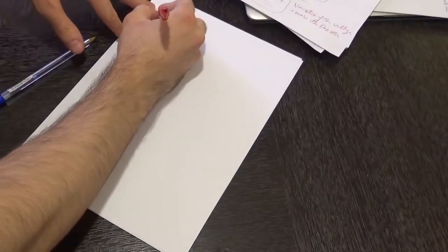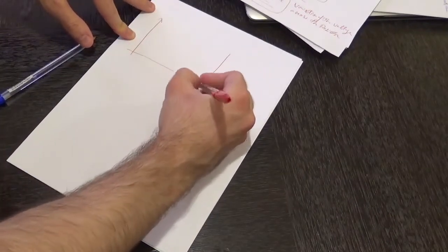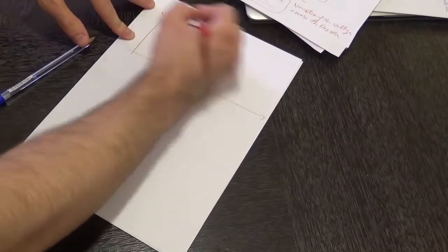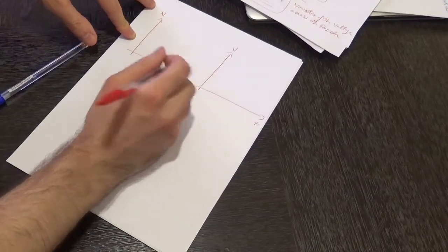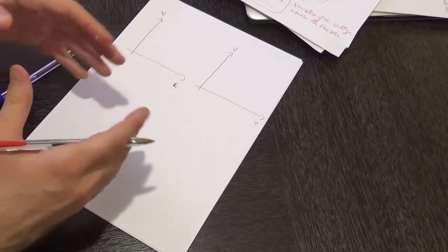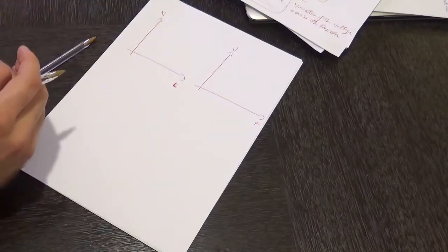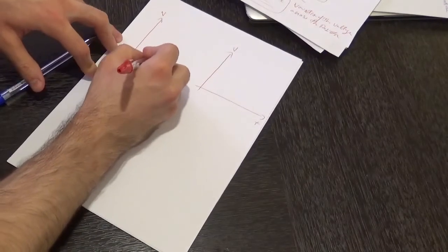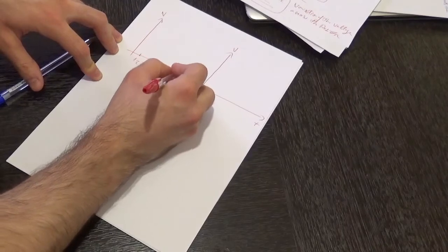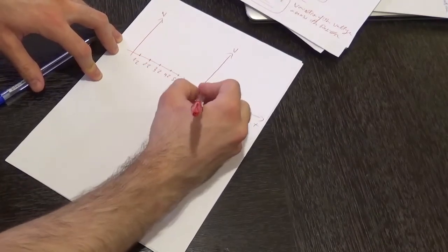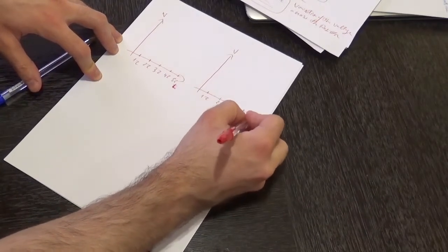Let's consider that we have the following two graphs for which we are going to represent the variation of the voltage across the capacitor and across the resistor. Over here we have the voltage versus time, and the time is going to be none other than the time constant, the time it takes the voltage across the resistor to discharge to a certain percentage, and the time it takes the voltage across the capacitor to charge up to a certain percentage. So over here we have 1 tau, 2 tau, 3 tau, 4 tau and 5 tau. Also over here we have 1 tau, 2 tau, 3 tau, 4 tau and 5 tau.